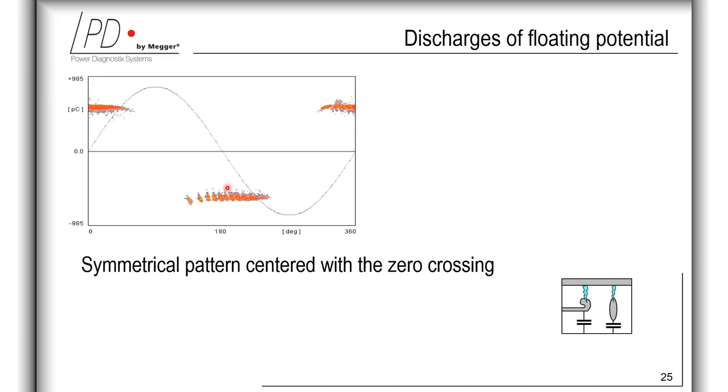And this setup produces discharge pulses whenever the electric field is changing. And for this reason, the activity starts in zero crossings, but leaves the 90 degrees and 270 degrees area unoccupied. And this is actually very similar to the concept with high electron availability that we have seen in the previous slides.